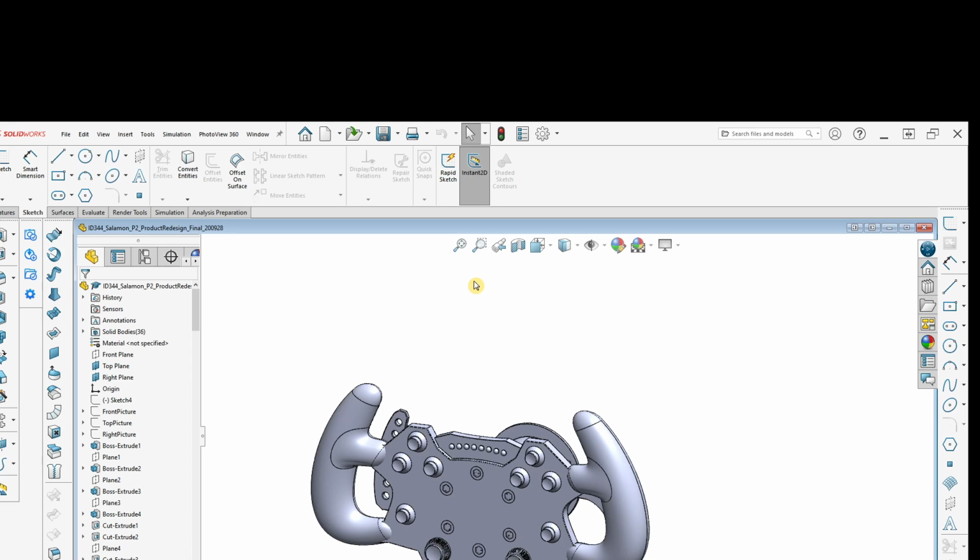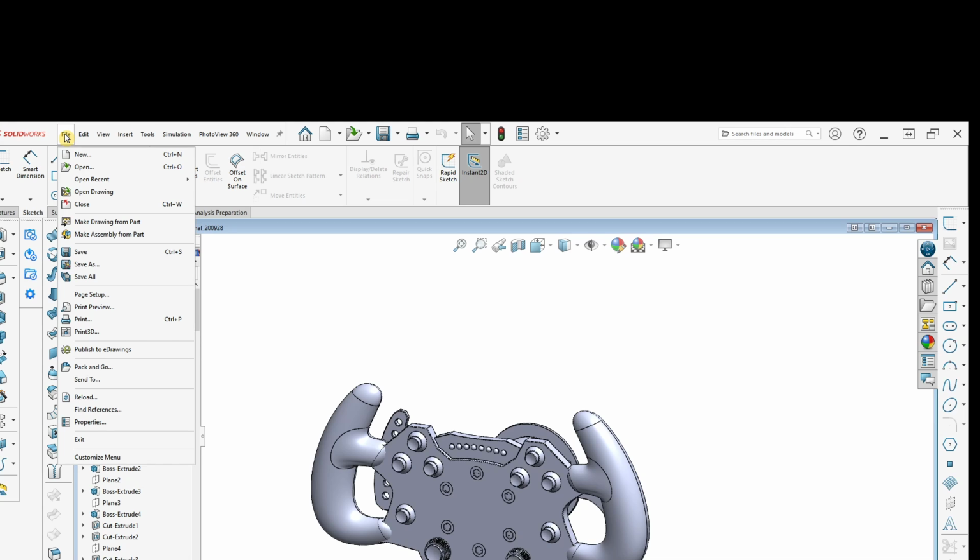That was also something that I kind of pointed out. When you send an assembly file, all the parts have to come, especially this main body, because the assembly looks at the individual components that go into the assembly, and then the individual components that are in the assembly need your parent model. That's kind of why doing the pack and go really helps. I'll show you that a little bit later again, because it will make sure that everything you need gets zipped into that one file.